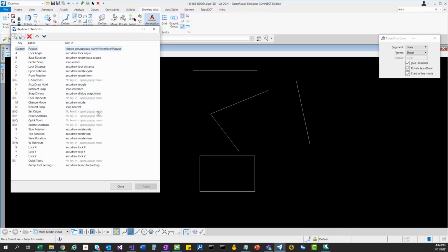I just want to mention the origin shortcut. For people in ORD, you have probably also heard of Civil AccuDraw, which this video is not going to go over, but the O key by default was taken over by Civil AccuDraw in the default settings. In regular AccuDraw, the O key didn't do anything, and you didn't actually have the origin for AccuDraw as a key-in.